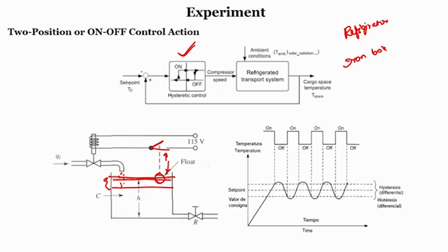To understand the system even better, say this is my set point, so consider this is 50 degrees. In the case of hysteresis or an on off controller, you always have to set two thresholds. Let us say this is 55 and this is 45. This is your higher threshold point and this is your lower threshold point.